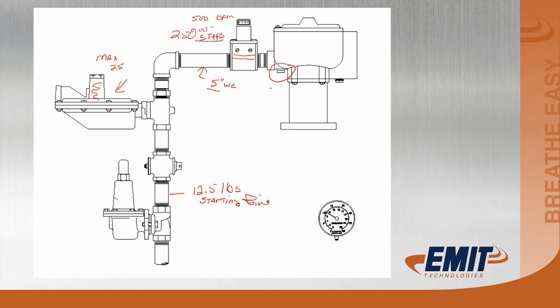You also want to look at this manual power valve here. Typically we'll set that at 50% to start off with. We don't adjust this again until we know where this is going to run, where the digital power valve will run when we're in the control cycle or control status. Okay. Now, once you get that set to 5 inches of water column, now you start putting a load on the engine.